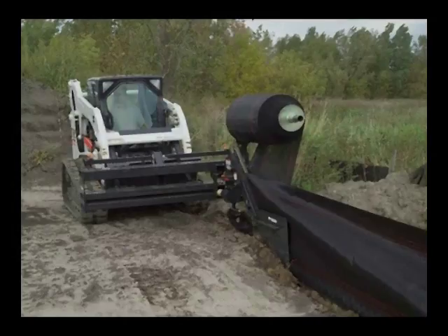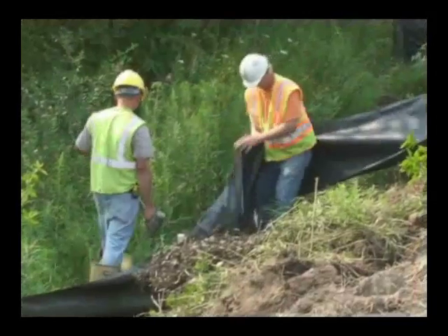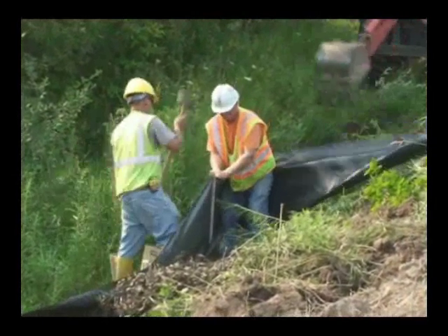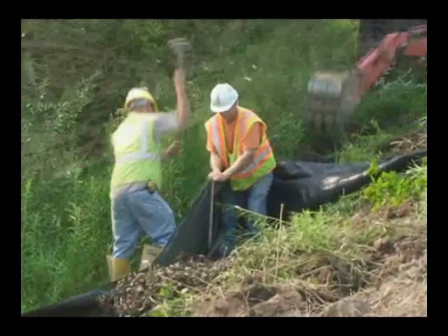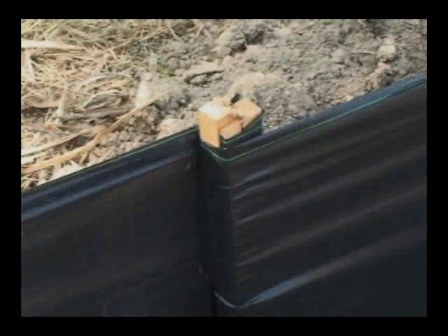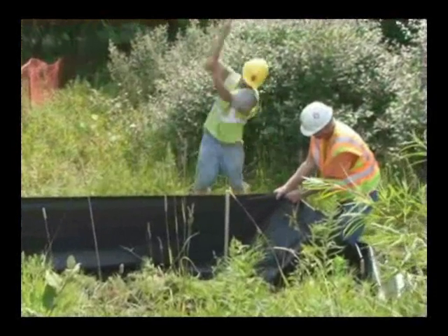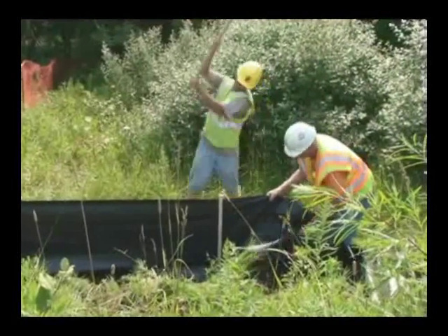The fencing should be trenched in to a depth of 6 inches and backfilled with the stakes on the down gradient side of the fence. The fabric should be taut so it does not wave in the wind. If more than one course of fence must be joined end to end, the ends should be wrapped so there is no gap between courses. If possible, locate the silt fence away from the toe of the slope to enhance ponding and settling.